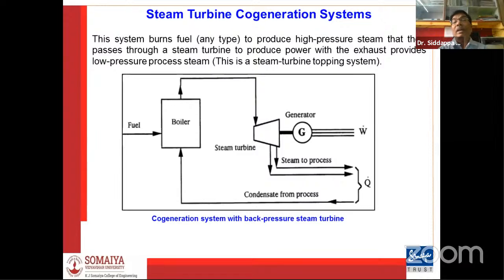And what's the purpose of tapping the steam at a high pressure and high temperature, or high enthalpy level? That high pressure, high enthalpy steam you are going to use for different heating applications or some different processes. But anyhow, once the steam is expanded from high pressure to lower pressure, the specific volume is going to increase.